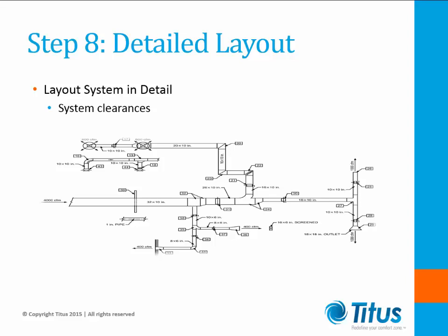A good design practice is to include a section detail on the design drawings with designated zones for fire suppression, ductwork, and lighting. If rectangular ductwork is being utilized, it can be transitioned to larger aspect ratios to fit over impediments or high ceiling areas. As a rule of thumb, though, I never exceed an aspect ratio of 4:1.